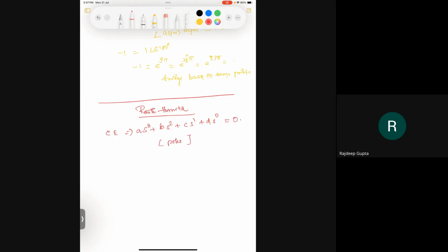If this is a normal polynomial with order less than 3, we can straight away find the roots of this polynomial, that is the poles, so that we can say whether the system is stable or not. But in cases where the order is higher than 3, we need another method, and that is where the Routh-Hurwitz criterion came to the rescue.